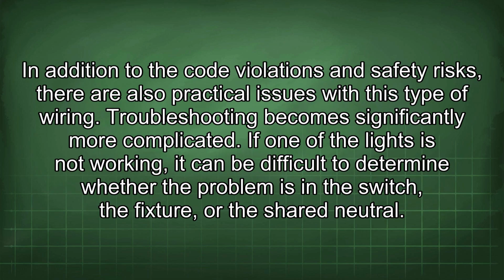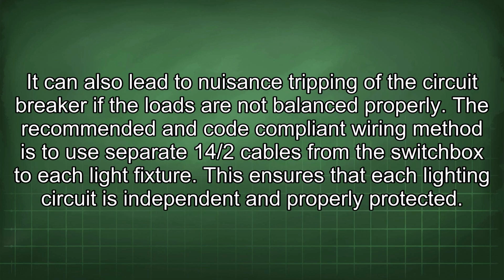In addition to the code violations and safety risks, there are also practical issues with this type of wiring. Troubleshooting becomes significantly more complicated. If one of the lights is not working, it can be difficult to determine whether the problem is in the switch, the fixture, or the shared neutral. It can also lead to nuisance tripping of the circuit breaker if the loads are not balanced properly.